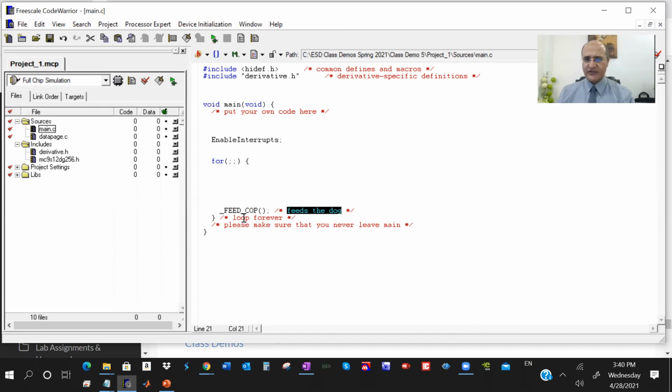Yes. Simply, it's a timer. If it overflows, it will cause the controller to reset. So we don't want it to overflow, so we reset it. We feed it here. There's a function that resets the watchdog timer. Okay, the watchdog timer timing, you can check it in the data sheet if you want to use it. You can configure it from a few milliseconds up to 2 seconds long to cause the reset. It's not our core business today.